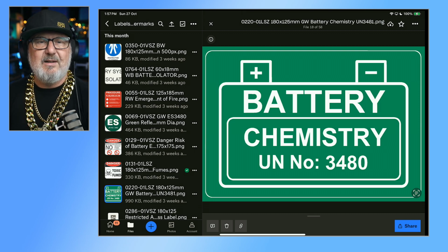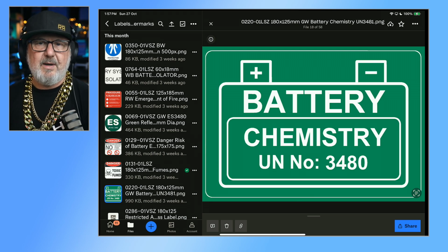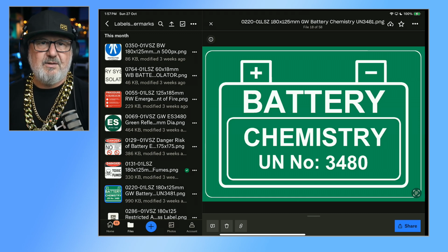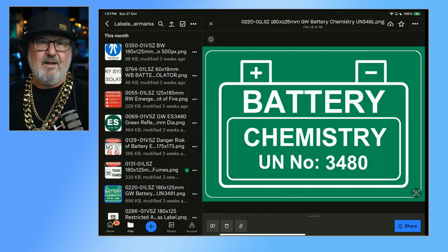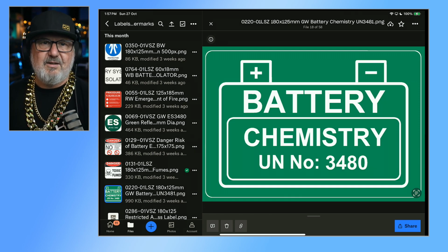Now, it's a requirement for any battery system that's installed under 5139, the battery standard, which is for installation of battery systems over 1 kilowatt hour, up to 200 kilowatt hours, over 12 volts, up to 1500 volts. So pretty much every residential and CNI system. And even if you've got a system that's over 200 kilowatt hours, if per unit it's 200 kilowatt hours. So if, say you've got 5 200 kilowatt hour units, you've got a megawatt hour system, each of them is still covered by this standard.